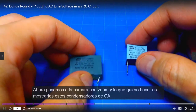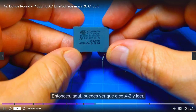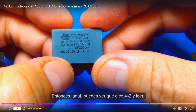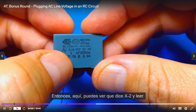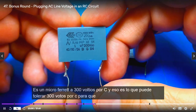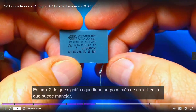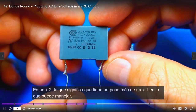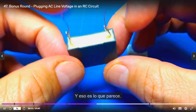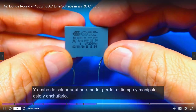Now, let's go over to the zoomed camera. What I want to do is show you these AC capacitors. This one right here, you can see it says X2 on it. And you can read around, it's 1 microfarad at 300 volts AC, so that's what it can tolerate, 300 volts AC, so we know we're safe at our 110, 120 line voltage. It's an X2, which means it's just slightly higher than an X1 as far as what it can handle, and that's what it looks like. And I've just soldered on here so I could mess around and manipulate this and plug it in.